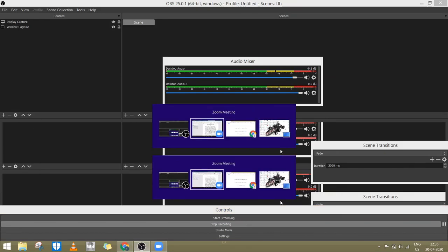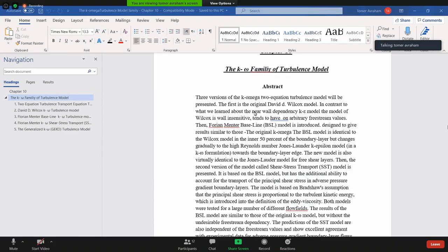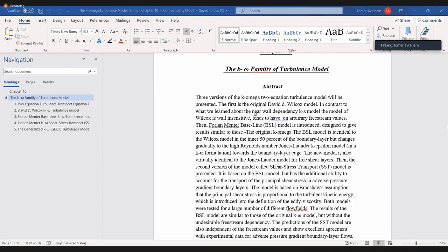The antisymmetric part would be, let's say, some kind of factor 1/2 times the u dy minus... is the rotation vector, the rotation tensor. So in the linear Boussinesq hypothesis in two equation models, we don't have the effect of rotation at all. That's the first thing.